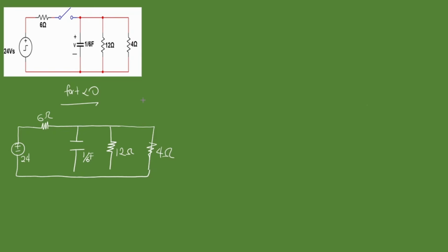What is happening? What do we do with this information? Remember what we said about capacitors, that our capacitor, when it's connected to a supply voltage, begins to charge up. That means positive charge builds up on one side, negative charge is built up on another side. So this means that current can't flow through a charging capacitor. Meaning your capacitor becomes what you call an open circuit.